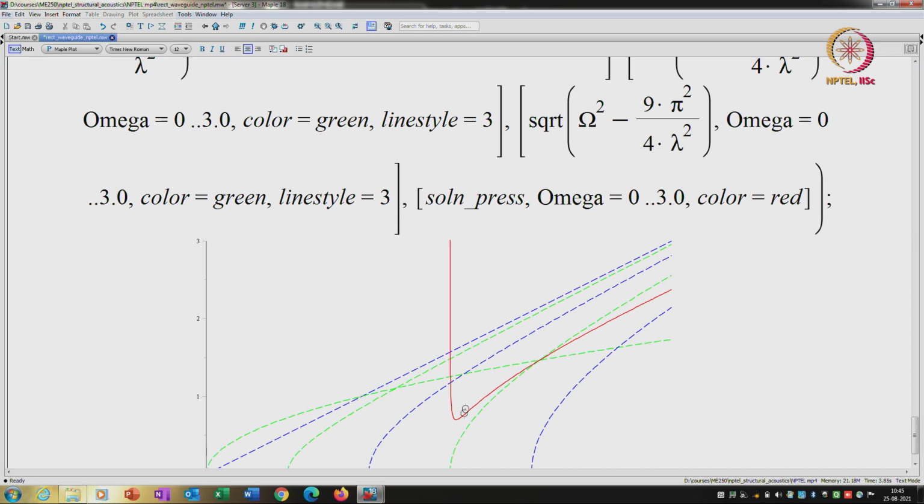Below this crossing frequency, one critical frequency, it goes through that point which is the crossing point between uncoupled flexure and that pressure release, and then it transits above, close to the pressure release curve.